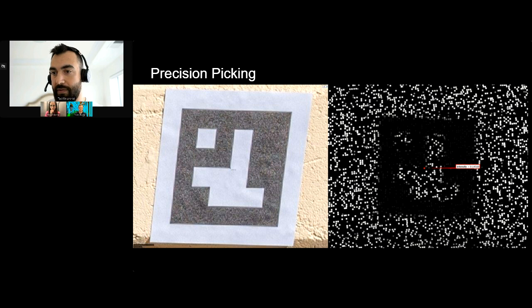In this case, I used the April tags, which are very useful for many other things. But you can see here that with the photos, you have a lot more precision in picking that point that's right in the middle, because from just a point cloud, you're left with the points that you see. So the intensity and the color that can be added to laser scanning helps to find where that target is. But there's some measurement error there. Where are you going to click, and where is that exactly the center?